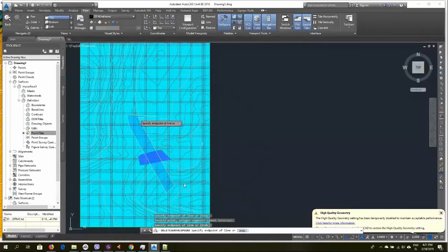Now it's selecting the points. So I'm just doing this point surface edit so that I can show you how to remove the point cloud definition from this surface. By removing these 3D points, we will remove the definition of this part of the surface, so there it will be just interpolated. So there it will be just some Delaunay triangulation of the neighboring points.